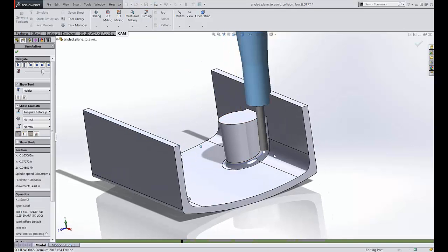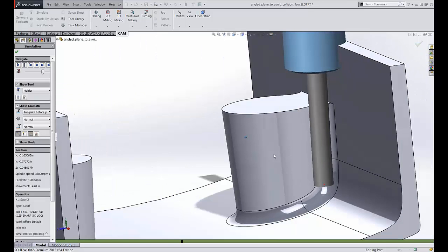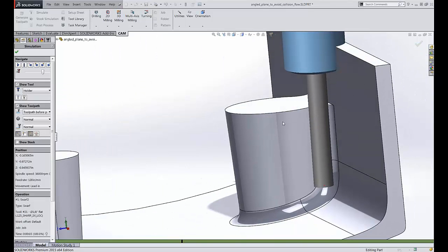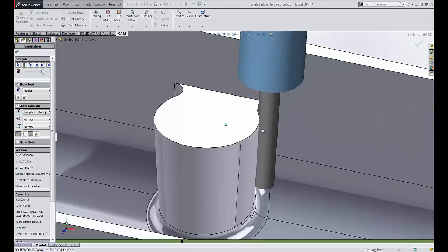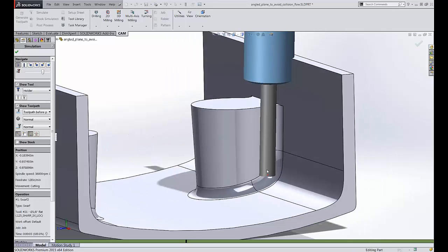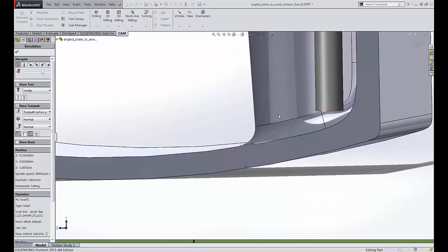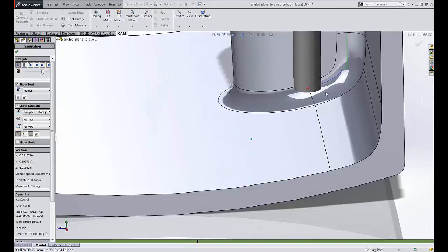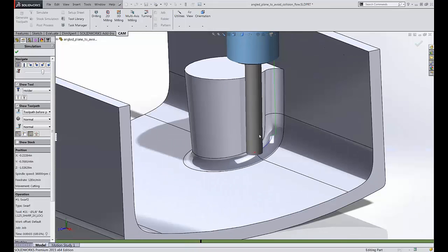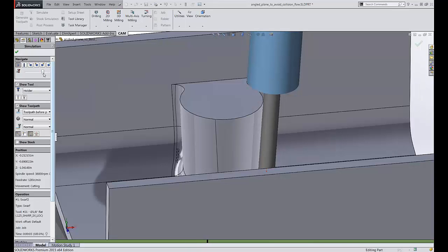So the toolpath itself is pretty good. It's actually really great. It's basically perfectly aligned with this starting edge, and I did absolutely no configuration on this at all. I just built this up, and it's perfectly tracing. I don't know if you can see that. It's perfectly tracing the fillet. In this case, I did a good job selecting the tool because it's smaller than the surrounding radius, so it doesn't gouge. It's going to trace that perfectly.